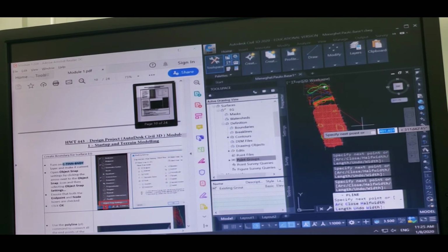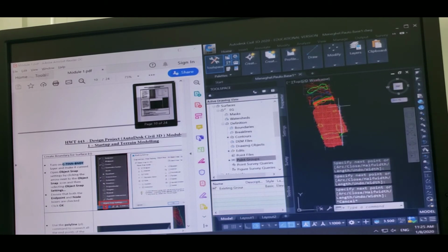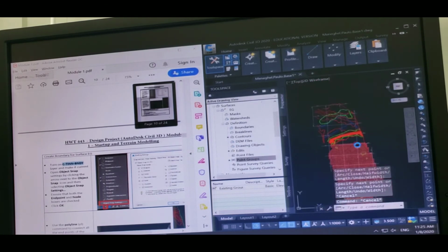It's one polyline. If you make a mistake and you make two polylines, what can you do to fix it? You can join it, right? And if it doesn't join, you can just edit it. Because you're snapping to the node of the point, you might have to flatten the line afterwards because you might have some elevation, okay? And you don't want to have elevation at this time. Anyway, you're going to be doing this, boom, boom, boom, all around. I'm not going to do it because you know how to do that, and I'm lazy.